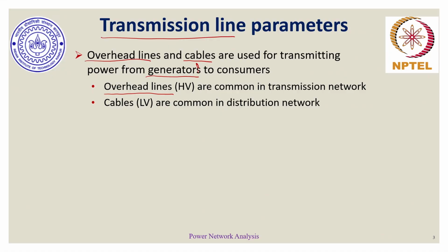Whereas for distribution networks, the voltage level is scaled down by step down transformers which get their power from the transmission network, because not all of our loads can consume power at high voltages. So we need those distribution networks, and mostly from the perspective of aesthetics, we often see cables being placed instead of overhead distribution lines, although certain cities still have overhead distribution networks.